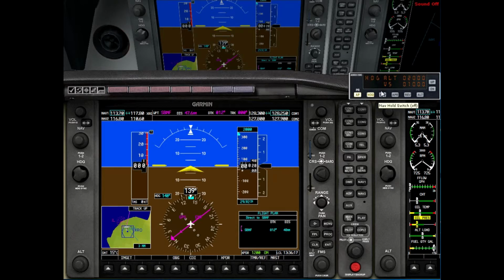And to switch on the flight plan we set on the GPS, we press NAV. So when you put NAV here, the HDG is going to be off because the aircraft goes automatically to follow the flight plan we set. We are going to make it in the air as well and see how it's going to work. We're going to leave HDG to take off.